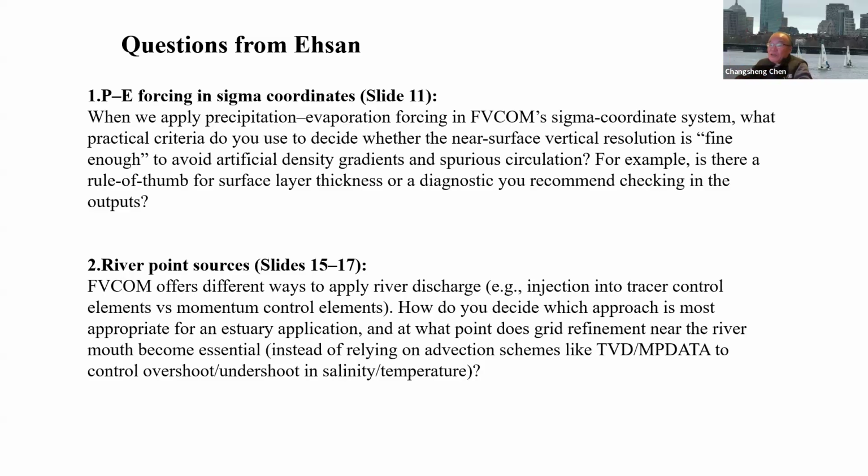That's why I suggest you use the S coordinate, because with S coordinate you can guarantee the surface is uniform. In the shallow water, even if it's not uniform, you have more layers in the shallow water and can have a fine resolution, but at least on the open ocean side, it must be uniform.